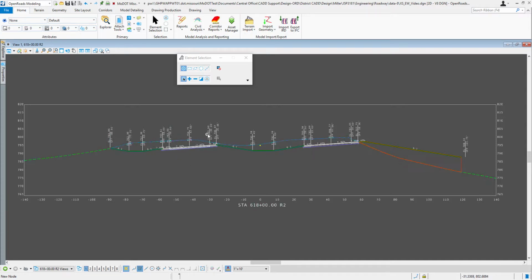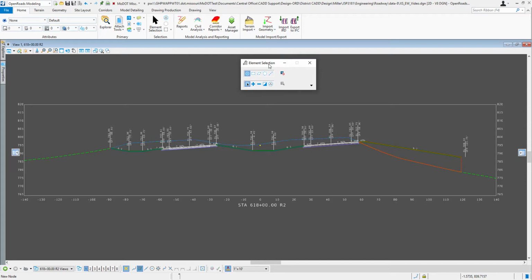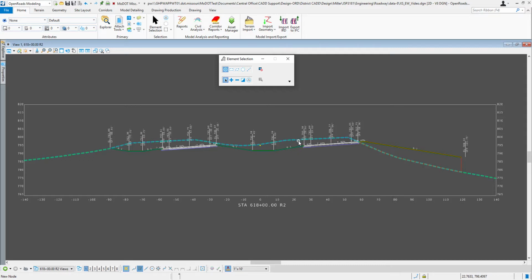It's giving my elevation and offset and all my slopes because we set that annotation up. And you'll also see there's a shape that's kind of created through here. And it's got a cyan color to it that represents our earthwork. Okay, and the cyan color is the cut, the blue cut, and then the red is the fill. And we're working on this error here where it's labeling where it got clipped. Bentley's working on that. But getting back to the process, we want to see some calculations in here, and there's no calculations for our earthwork whatsoever. We do have shapes, but we don't have any calculations.